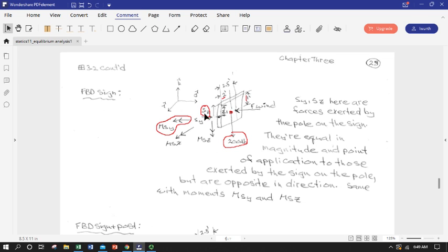And so we've already identified a couple of reaction forces just necessary to account for the sign's weight. Okay, now we include the wind load, and so we've put it appropriately where we're told it goes, and so it's going to basically push the whole sign backwards in the J direction. So this whole thing's going to go backwards. So we're going to need to oppose that. The post is going to need to oppose that with an S sub Y going back the other way.